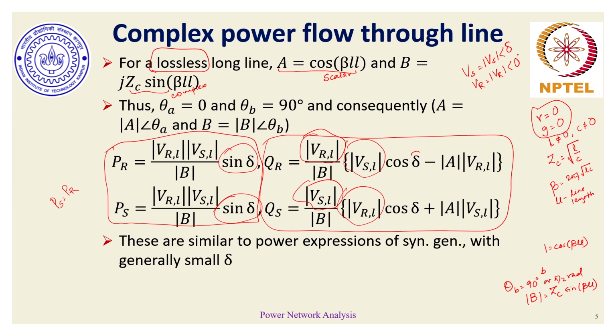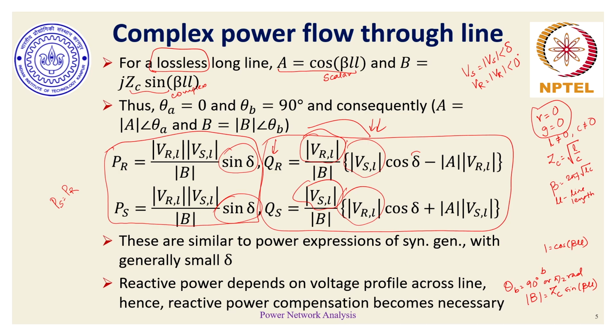It often tends to be close to 1, or 0.999, or 0.98, or 0.7 at best, depending on the delta value, which is not very drastically different. That's the reason why reactive power flows have more to do with voltage magnitudes, and why reactive power strongly depends on the voltage profile. It has strong correlation with voltage profile.